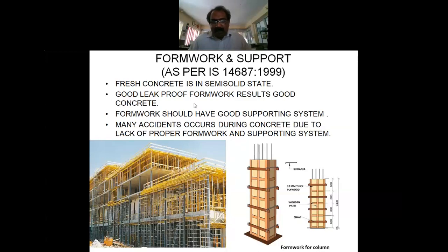The fresh concrete is almost semi-solid. If you pour the concrete on the formwork, the very simple thing is the concrete should not leak during compaction. Many accidents happen because of poor formwork.